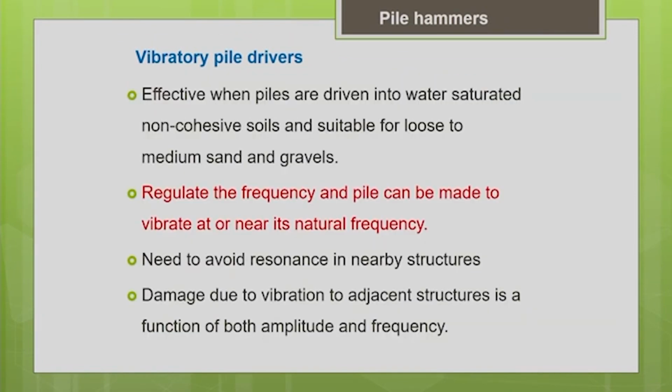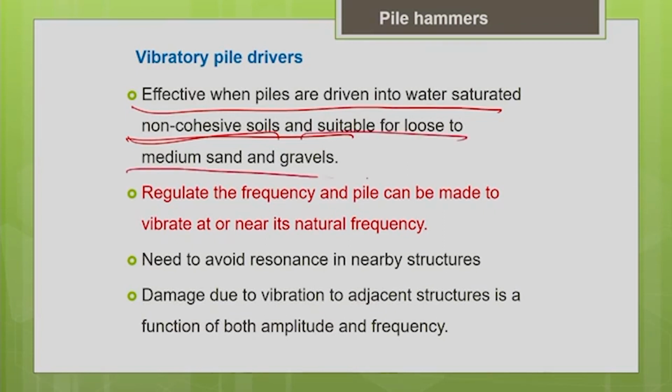So, for what type of soil is this more preferable? This is more preferable for non-cohesive soil, because that will respond easily to the vibration when compared to cohesive soil. This is particularly the right choice for water saturated soil. It is effective when the piles are driven into water saturated non-cohesive soil and suitable for loose to medium sand and gravel, because these kinds of soil will respond well to the vibration.